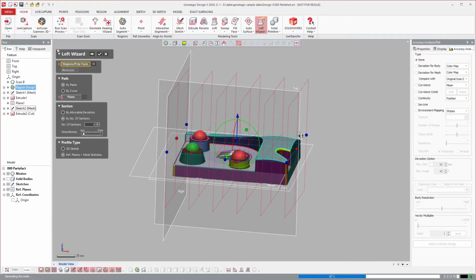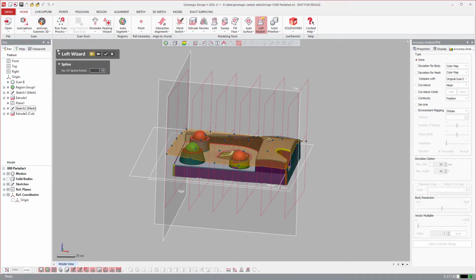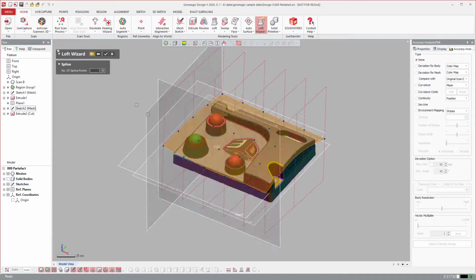And that allows me to inspect it and make sure that the lofted surface is what I want it to be before I create it. So you'll see here, this is the lofted surface. Now, if those splines are not high enough resolution, I can come in and I can make these splines 10 noded splines or 15, and that adds resolution to the surface itself.